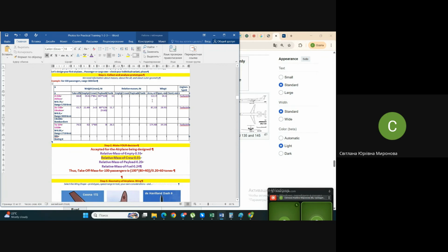When it comes to real geometry, you may make two different tables, like one for masses and the other for geometry. Again, all information you have found for the geometry of your airplane goes in one group of columns. Fill it or not, depending on what you have really found. Don't invent statistical data.